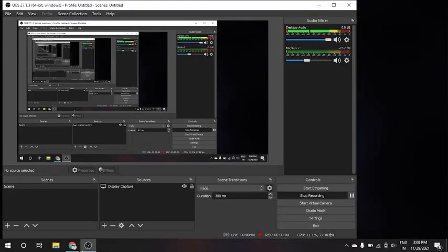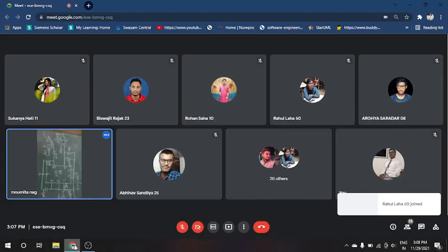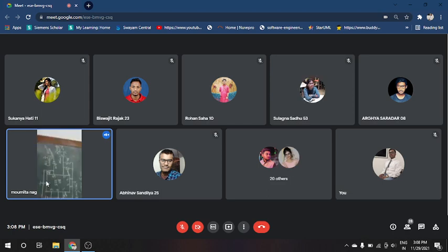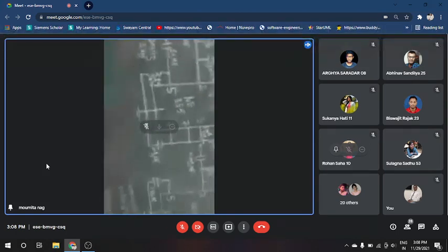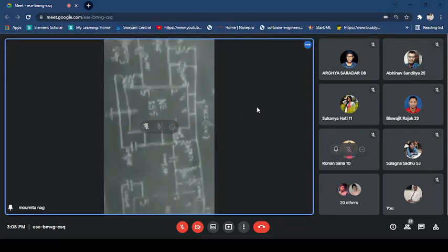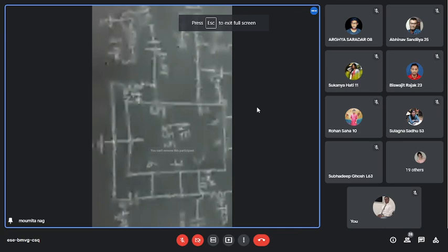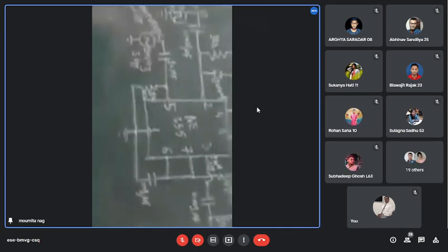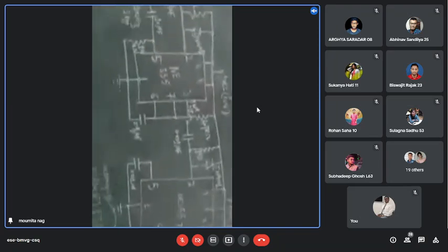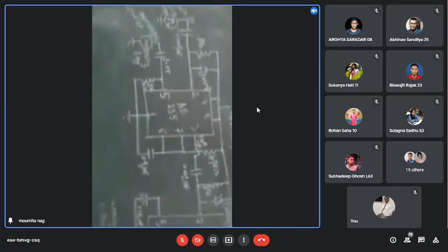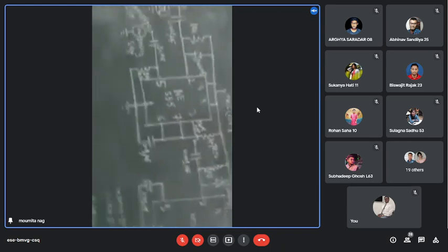Circuit working in astable mode. But today the circuit is quite different. Now the NE555 timer is working in monostable mode. There are two 555 timers. The first circuit is for generation of PWM and the next circuit is for generation of PPM. Both the timers are working in monostable mode.